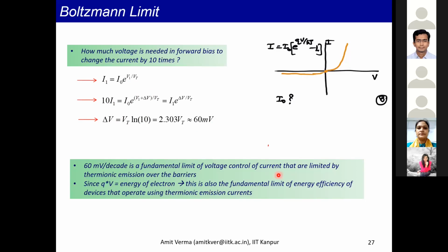And this is currently the most important topic in semiconductor research, especially logic scaling, that how do we make devices switch at steeper than 60 millivolt per decade. So there are a lot of approaches by integrating ferroelectrics in the gate stacks, what's known as negative capacitance FETs, by integrating phase change materials in the source or drain of the FET. These are called phase transition FETs. There are impact ionization FETs. There are tunnel FETs. So there are many, many approaches for that. And it's a very, very important topic.